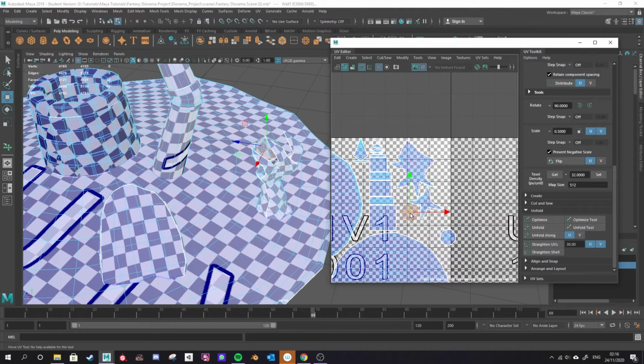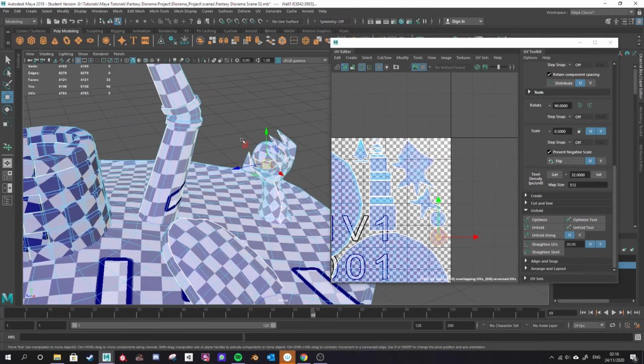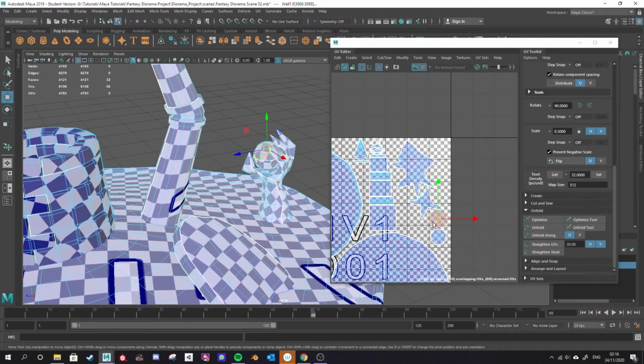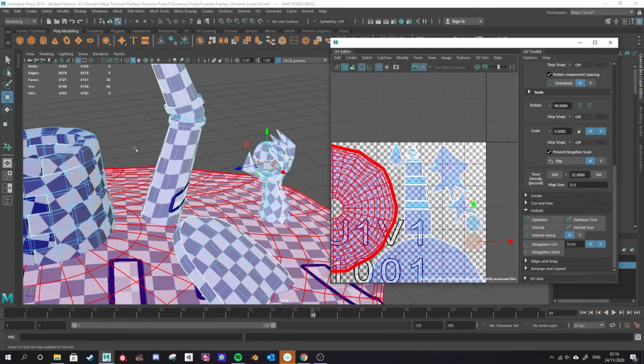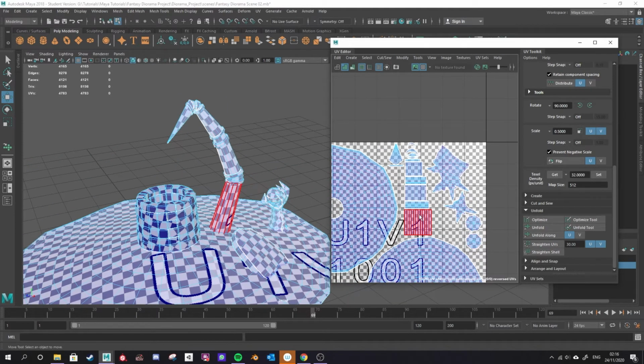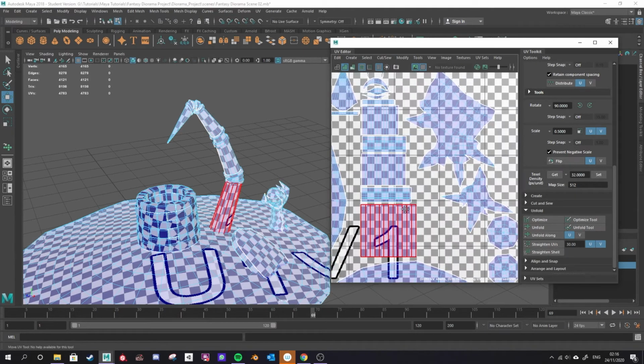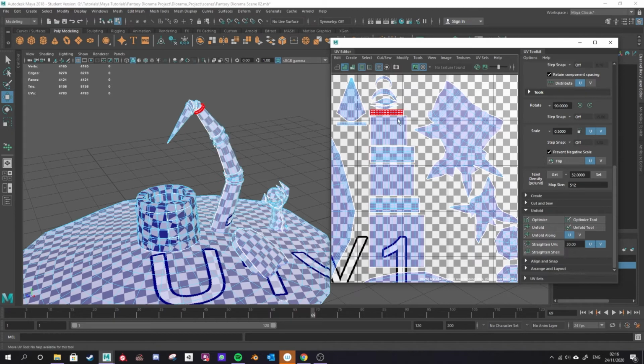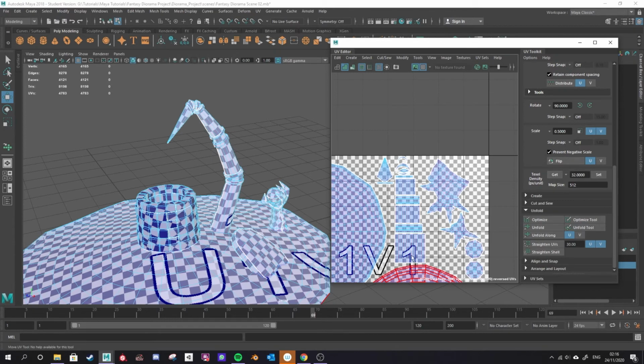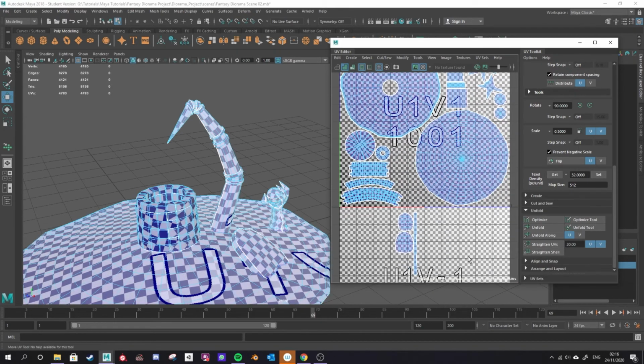You can see as well I'm making a specific order to the different assets. So for instance, on this orb, the top of the orb is up above the bottom of the orb in the order in my map. I also have the post here, gradients up from the bottom gradually to the top through the way I've laid out the shell, so I know exactly where I am when I'm painting. Say I want a gradient of dirt from the bottom rising up, and I'm hand painting this myself. I can start the dirt here and then make it tail off towards here, and I'll be able to do those gradients accurately because of the way I have my UVs laid out. So you'll pick this stuff up in time.